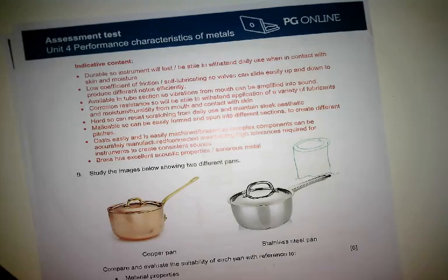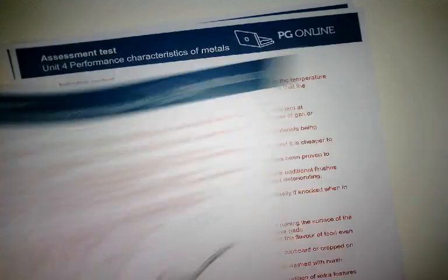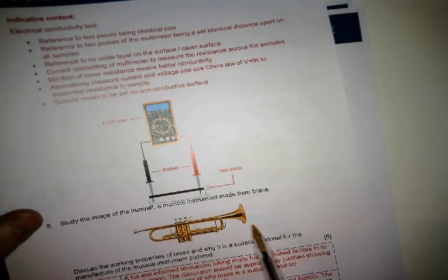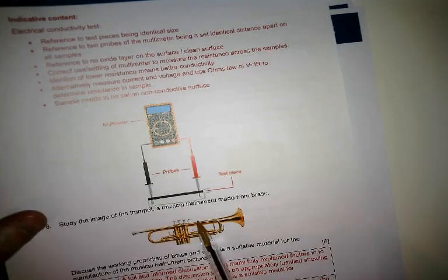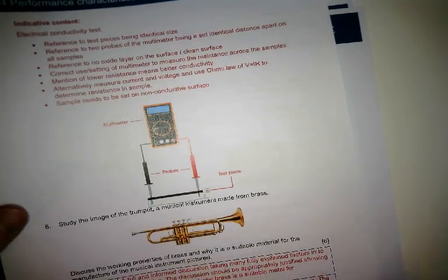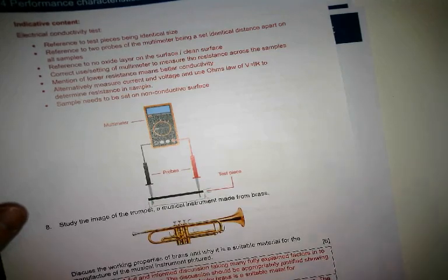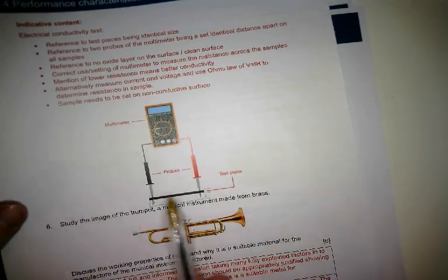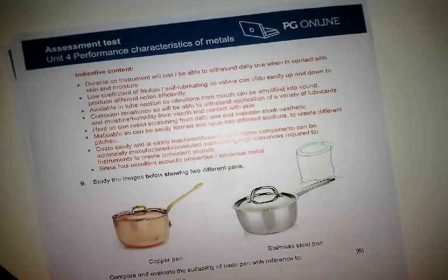Malleable, so it can be easily formed, spun into different sections to create different pitches. Okay, so the idea of spinning it to create the bell of the trumpet, it's on this sheet, sorry. This bit here would be spun, okay, and it's normally joined here onto the other tubes, but that's done on a machine and it's called spinning. It's almost like a lathe. Without cutting it away, it's pressed and formed using a roller and it's kind of shoved into place. Well worth looking at spinning, a very old-fashioned process, but still used for things like lampshades, etc.